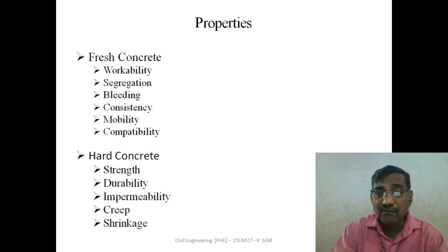The properties of fresh concrete are workability, that is the consistency of the concrete, the percentage of water added to the concrete for good mixing, transporting, placing, and compacting. That is called workability. It is measured with the slump cone test.